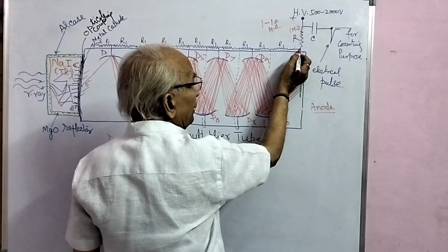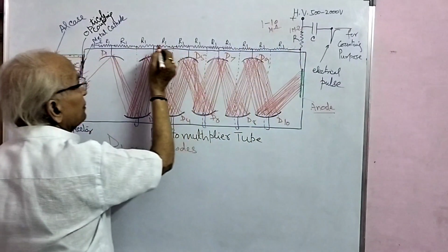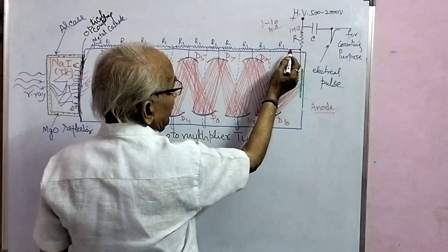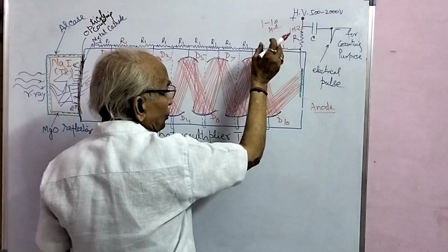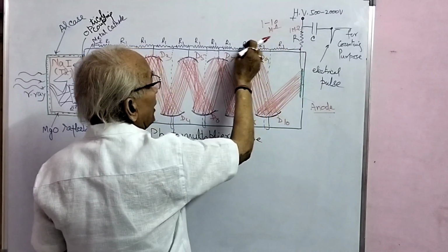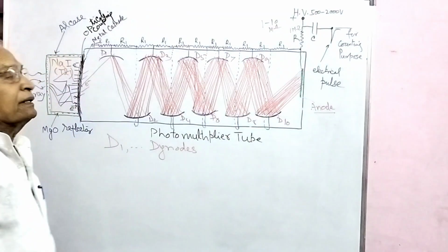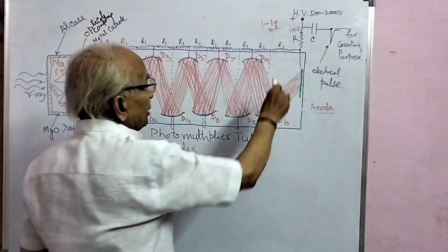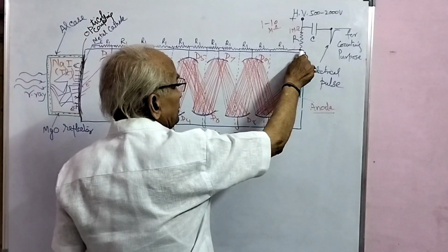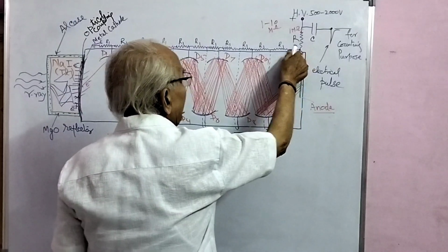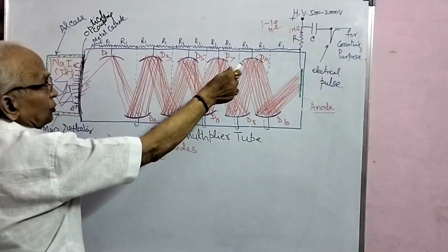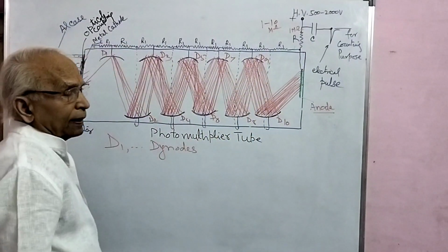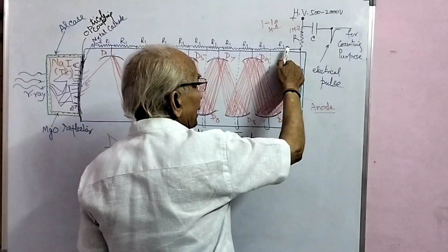And from here we have a resistance series. On this side it is earth, E. On this side we use resistances of equal value, R1, R1, R1, R1. A resistance in series, many resistances. This resistance here has some potential drop because this will send a current, since it is grounded. So if this is say 500 volts, you add all the resistances and you will get the current. That current will give an IR drop here.